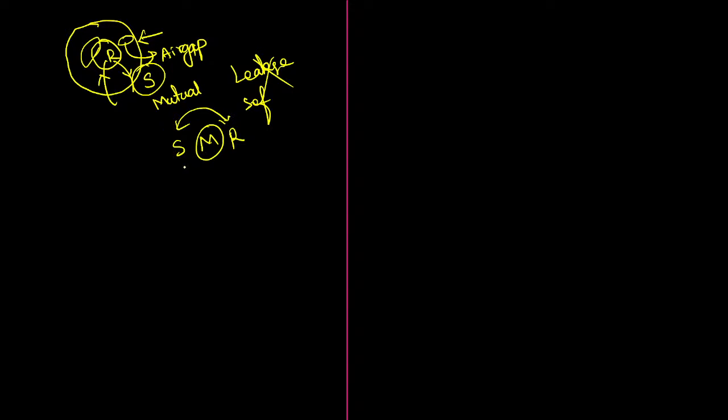Here, electrical energy is converted into magnetic energy, then magnetic energy is converted into mechanical energy. Similarly, the reverse process: in an alternator, first mechanical energy is developed, then converted into magnetic energy, then into electrical energy. So the intermediary is the main flux, or mutual flux. Without this flux, we cannot do any action in machines. So it is very important to give importance to this mutual flux. He is the supreme star.